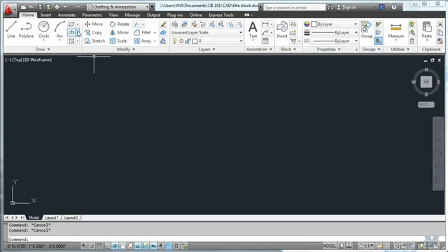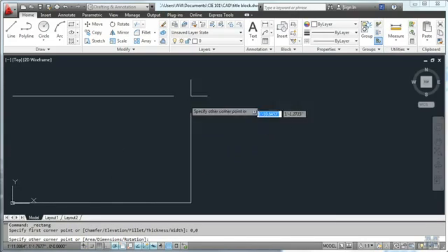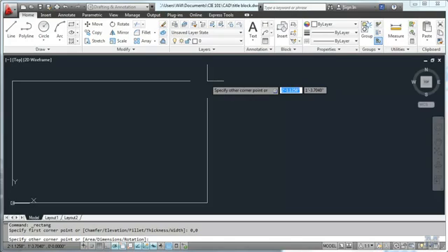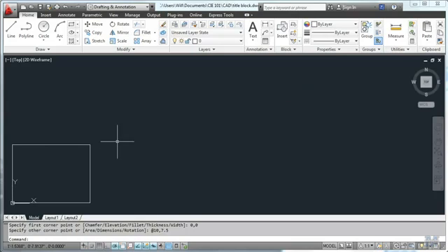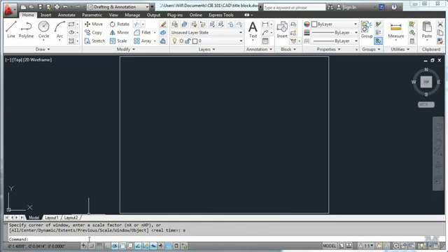Alright, CAD fans, in this video we're going to draw the sheet layout and title block we'll use on all our drawings. I've already done the limits and units commands to work in engineering, and we're starting a rectangle here. I'll start it at 0,0, and then the other corner is going to be at 10 inches across and 7.5 inches high, and so that will give me my sheet of paper. We'll zoom extents, and there it is.